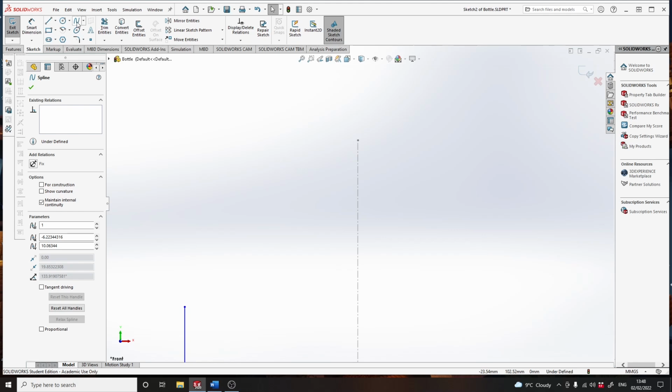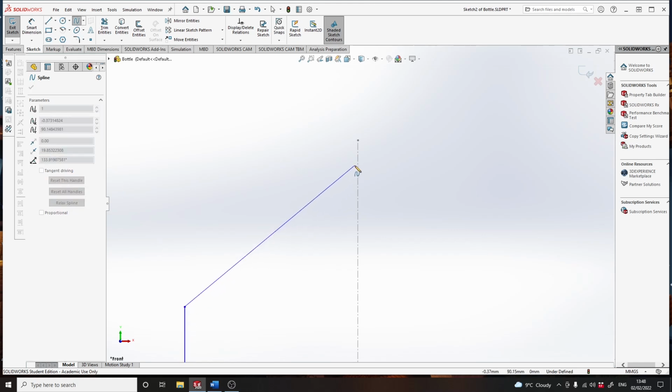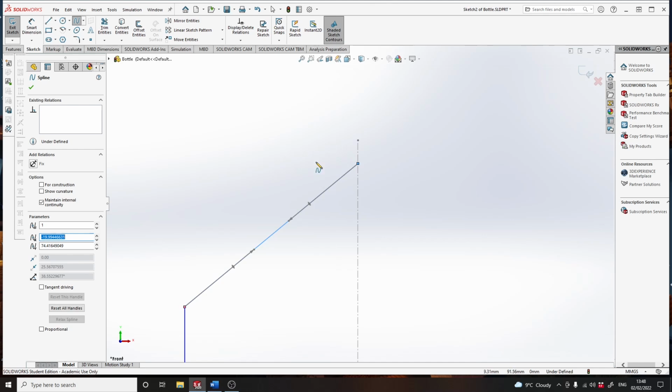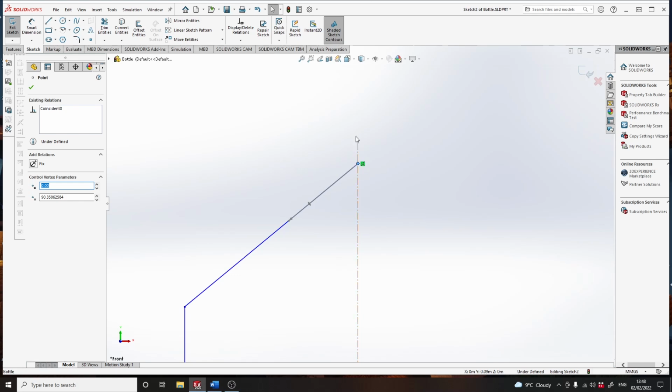So imagine you're putting this in and you connected it up, and that little yellow thing appears to tell you it's attached. Put it in, and if you've done that, what you find is now that is attached to this line, or it's got a relation, so a coincident relationship. And if you do this, you can't do the revolve easily. So what you can do is just go up there, click on that little icon, and click delete, and then it's gone. And when it's gone, you can just pull your line slightly off the edge there.